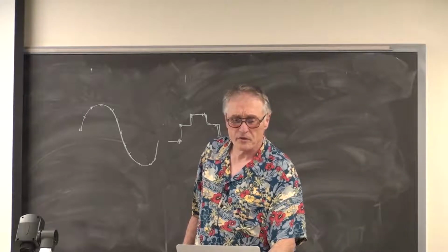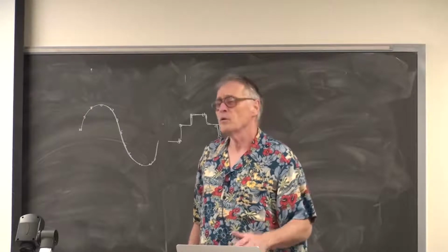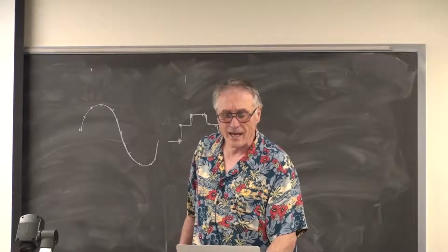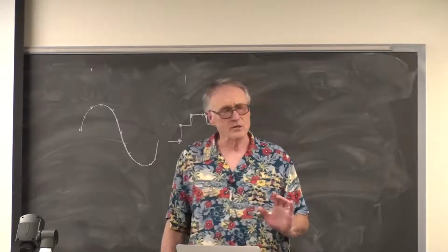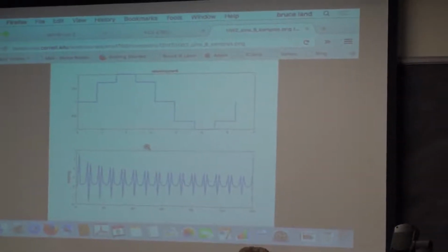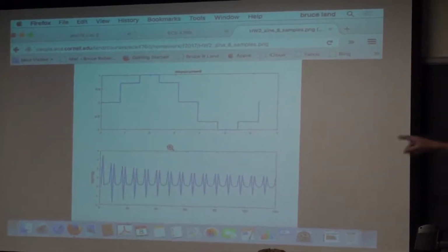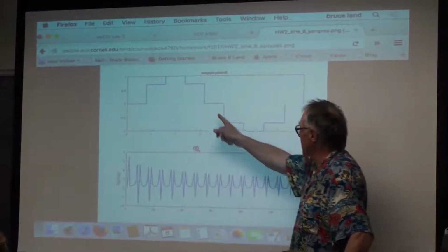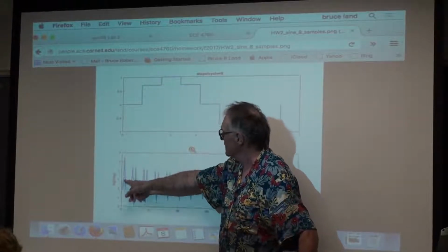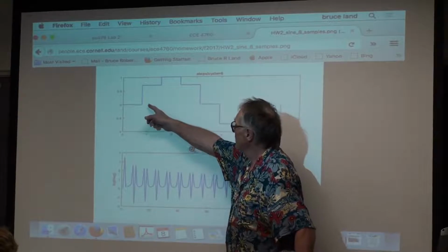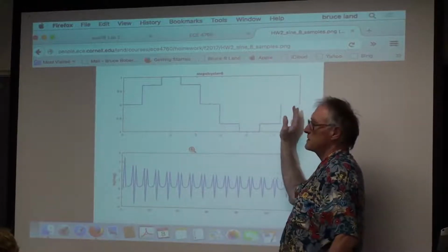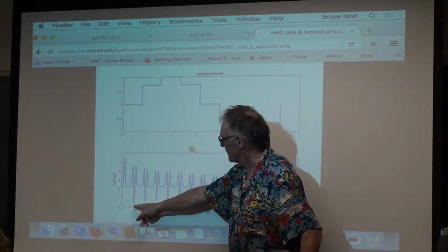So, all spurious frequencies must be minus 20 dBs from the main tone. 20 dB is a factor of 10. And that's over a range of 1 kilohertz to 6 kilohertz. So if we take a normalized image, normalized to 1 cycle, I don't care what frequency it is, it's 1 cycle. 1 cycle of 6 kilohertz, 1 cycle of 4 kilohertz, 1 cycle of 2 kilohertz. Whatever it is, it's 1 cycle. If we have 8 samples on that 1 cycle, then the spectrum is going to look like the true frequency, in this case exactly 1 per window, and then error terms that start right around the number of steps per cycle. So in this case about 8.